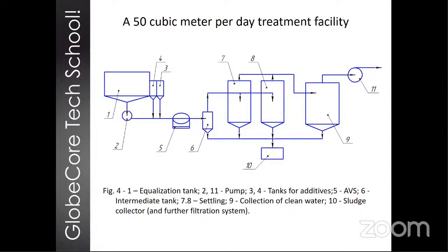So we can always recover almost 100% of the filter's efficiency by just washing them with water. And given the high chemical resistance of polystyrene against the effects of any acids in the water, the lifetime of the filter spans years. And the particles that we washed off in the form of sludge are then discharged into the sludge receiver, position 13, that is equipped with a replaceable container.